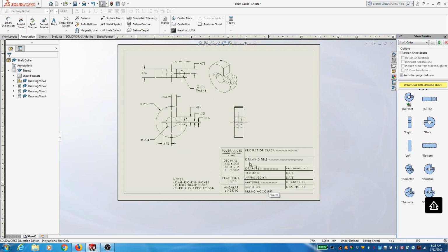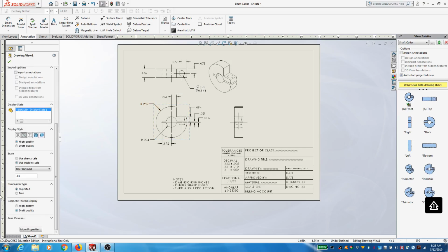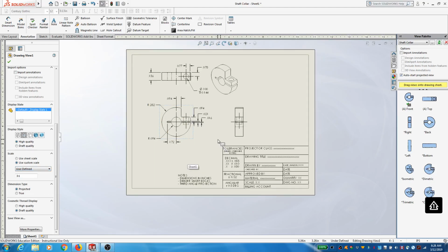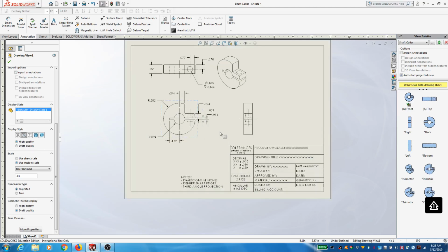The only thing left to do would be to fill out the title block, right? Making sure that I specify what the scale is. And just to remind you guys, I had to put in a custom 3:1. I used the user-defined custom scale because the options from the drop-down weren't as nice. But that's a somewhat tricky part, fully dimensioned. And yeah, good luck on this assignment.